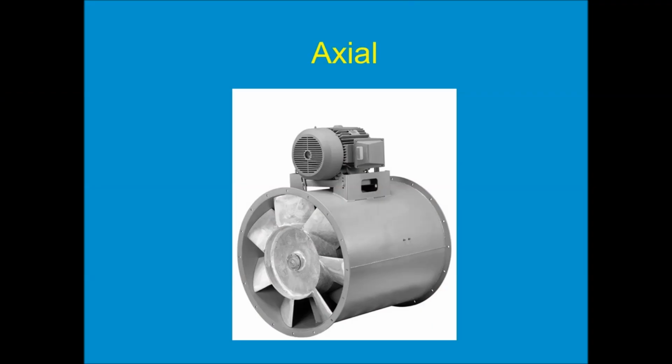The main feature about this type of fan is that the overall housing of the fan is just slightly larger than the impeller itself. As you can see, the impeller takes up practically the entire diameter of the fan. So in a very tight situation, a very cramped mechanical room, this might be the best choice because it has such a small footprint. But generally speaking, there are other options that can move the air more efficiently.